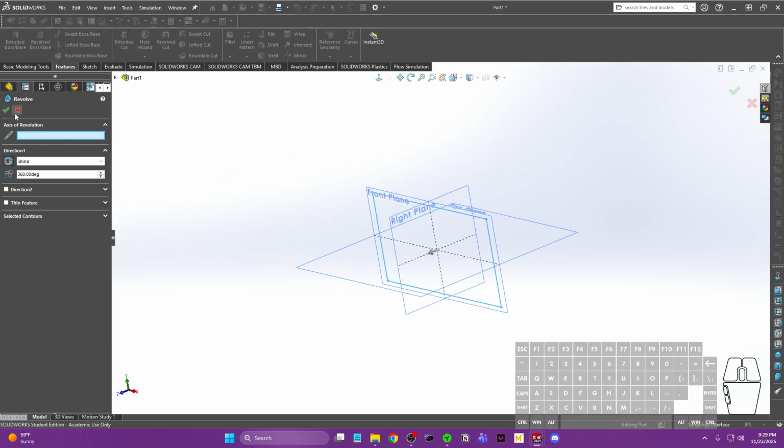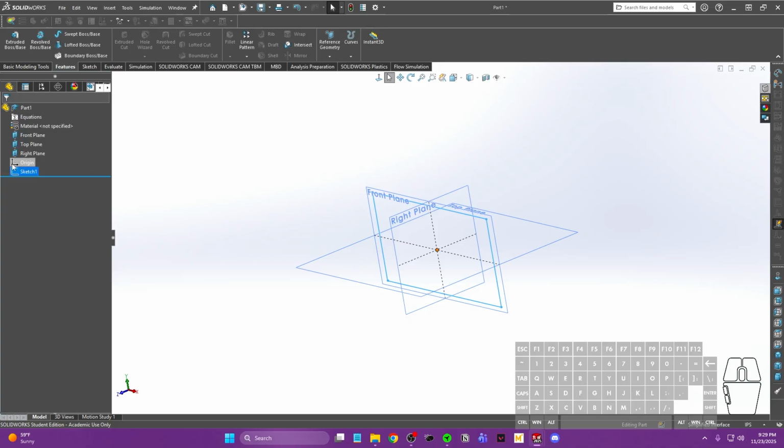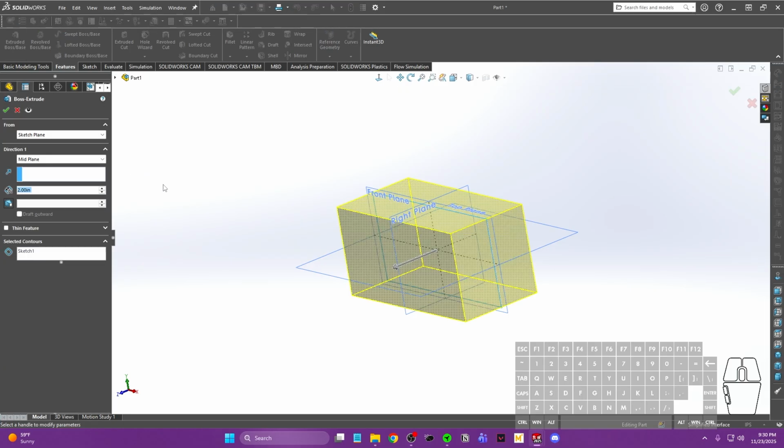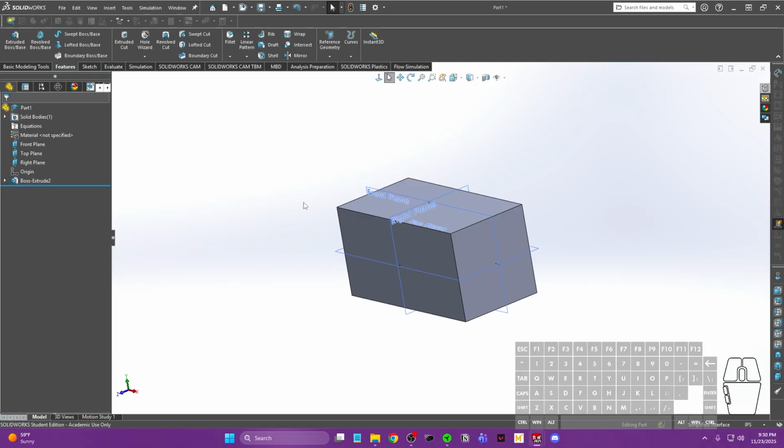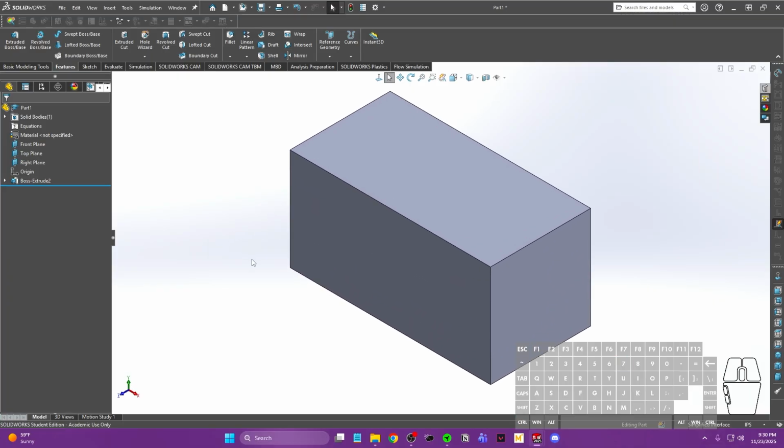Let's go ahead and I'm just going to cancel it. And we're going to go back to the extruded rectangle. It keeps the same parameters, so mid-plane, 2 inches. Alright, and from here, after I have established my first object within my part file, I'm going to go ahead and disable the view planes, because then it's going to get kind of messy. So back to my isometric view.